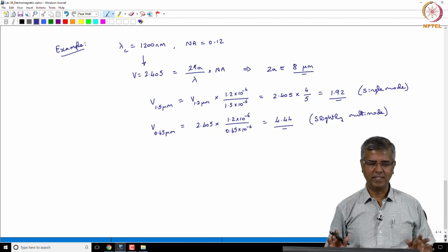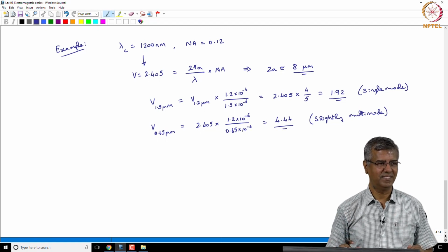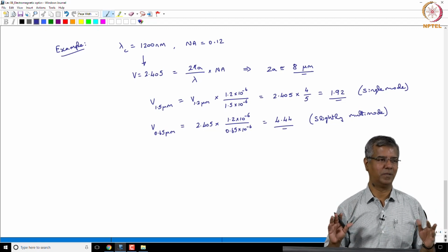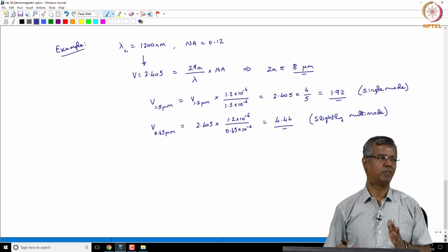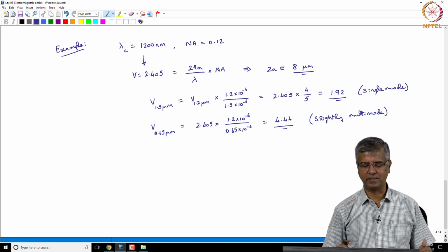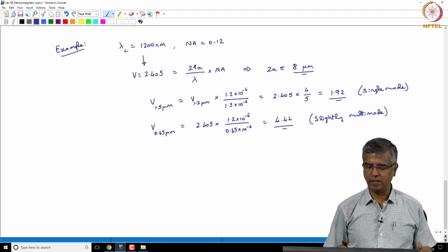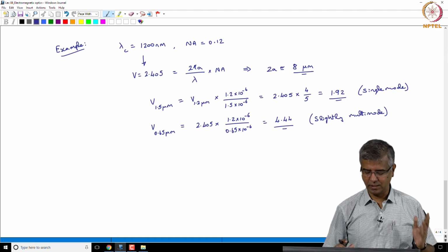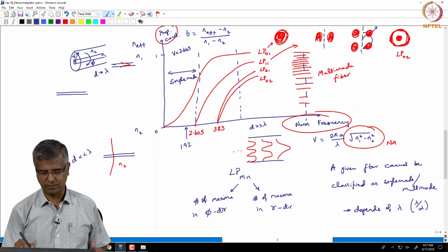Okay, so don't buy into things which say, oh, this is generally single mode fiber, multimode fiber. If they are saying single mode fiber, watch where the cutoff wavelength is and where you are with respect to the cutoff wavelength, and then you can decide whether it's single mode for you or not. So the question is what does the cutoff wavelength imply? It implies this particular point, right?